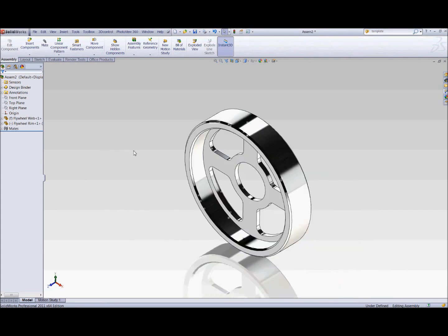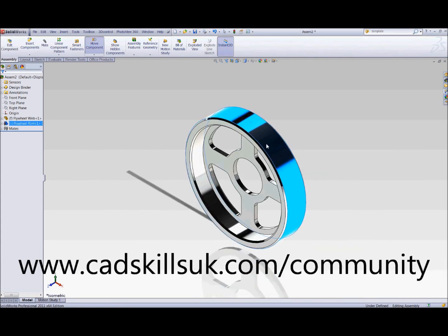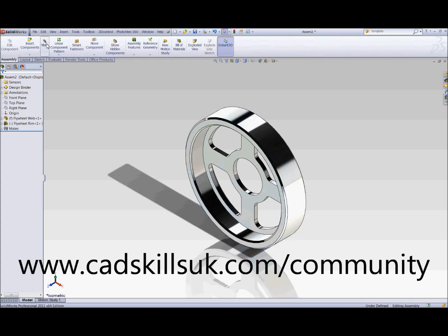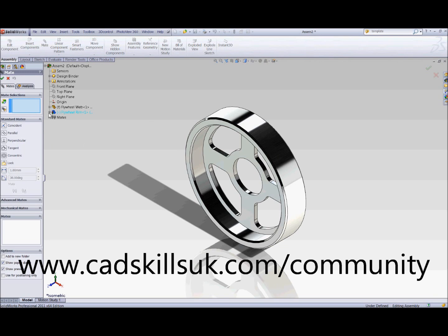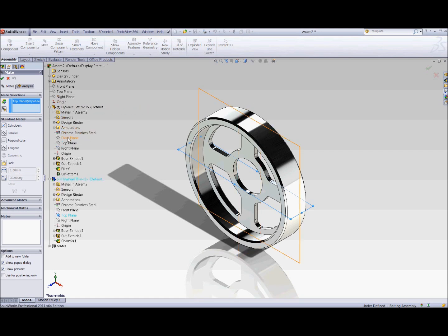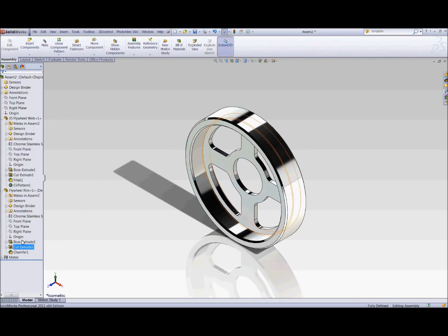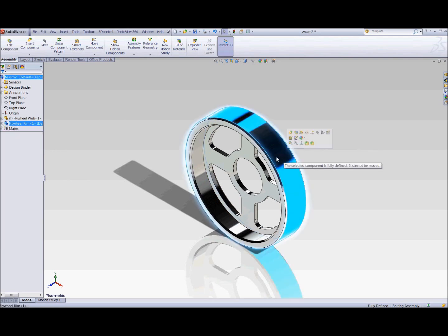Finally though, it looks fine, but we've still got a negative on the flywheel rim because we can actually rotate this around the outside. Difficult to see because we have a flat surface, but that's actually rotating. So what I'm going to do is mate, and pick up the flywheel rim. I'm going to go for a plane like so. And then I'm going to go back into my flywheel, and I'm going to locate that parallel to there. There we go, a coincident to that. Now that's going to be fully constrained, and the part won't move around the outside.